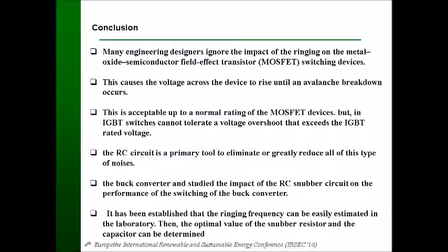The RC snubber circuit which we designed here can reduce the noise in the MOSFET. We also noted that in a MOSFET we can sometimes ignore the snubber circuit, but in an IGBT it is not possible to ignore it, and the stress should be reduced. And we have established how to estimate the ringing frequency in order to find the optimal values for the capacitor and resistor.